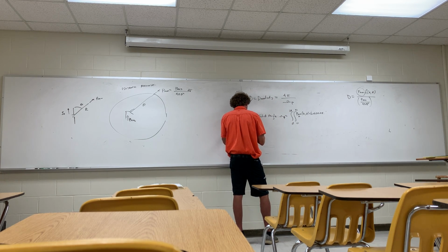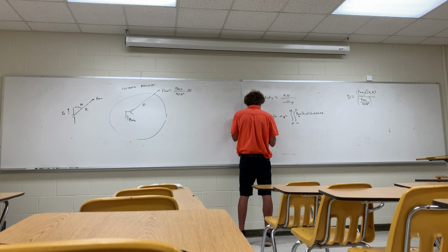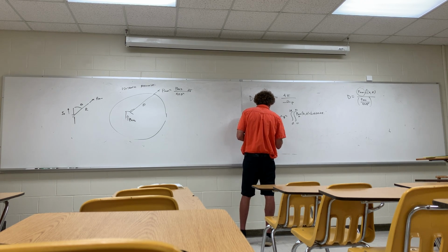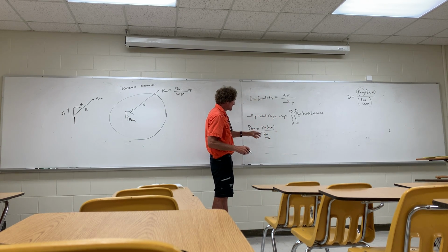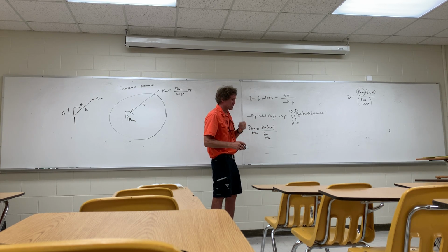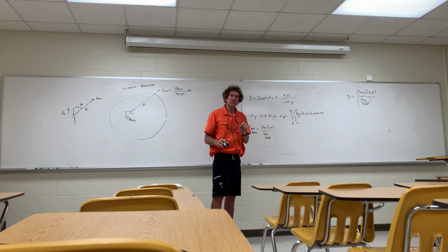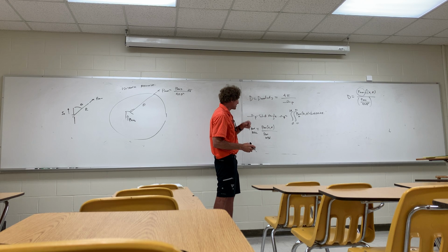When I take a look at the average power density normalized, what I mean is that you take the power density at any given point in space, so it'd be P average of theta and phi, and then you divide it by P average's maximum value at that range. And you can put an R in there, but it'll cancel. So this, when I say normalized power density, I'm saying that the largest value you can have is 1. And I'm gonna do an example in a second, all right? Because some of this, I think, needs a little exploring.